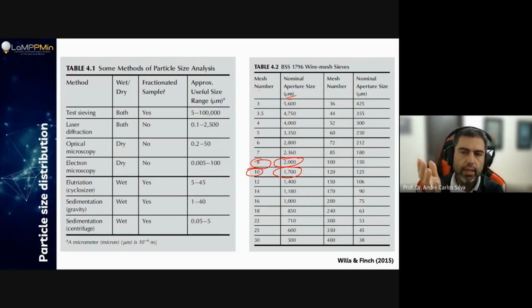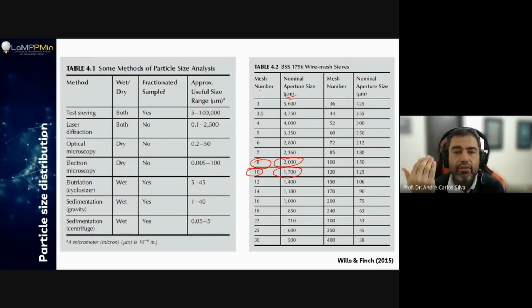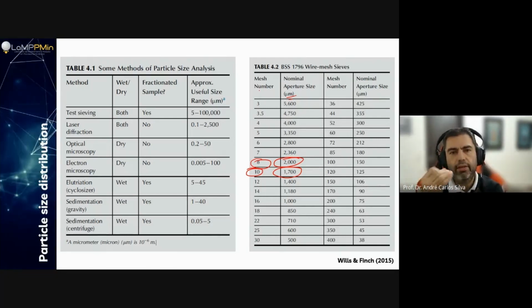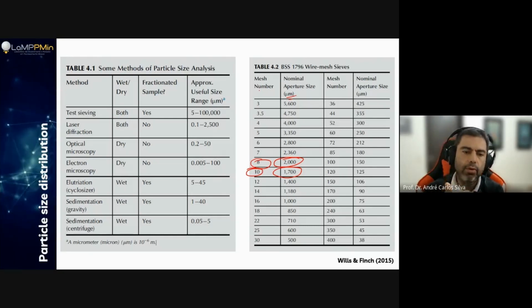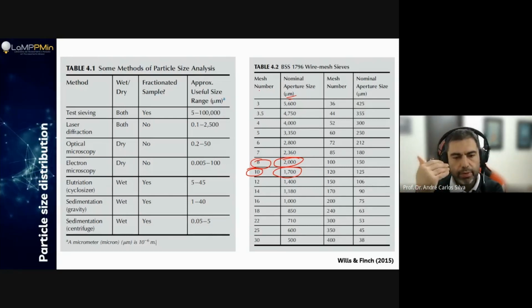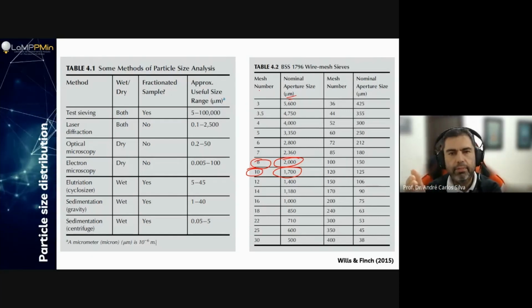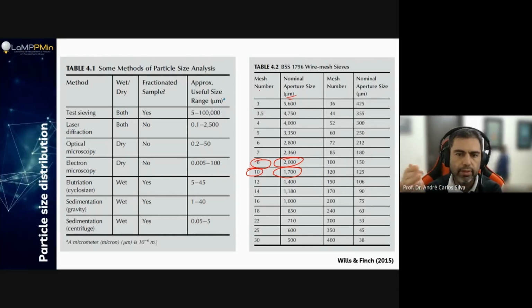Okay, it's the same. But below that, like 660, it's on the market even to 800 mesh. Okay, but it's impossible to have a really good sieving with this kind of sieve unless you add more equipment, for example, ultrasound, or water pressure. But for the daily basis and for the control of products that you actually produce in your processing plant, that doesn't work. Okay, I completely suggest you guys move away from that.